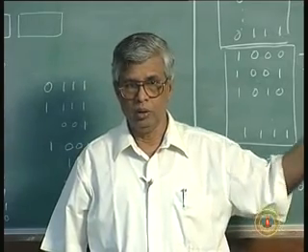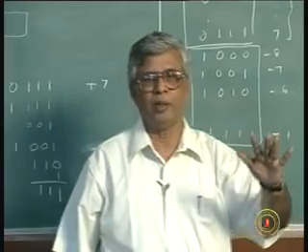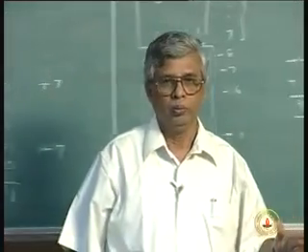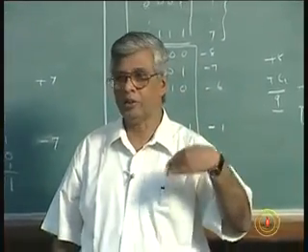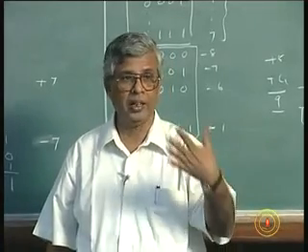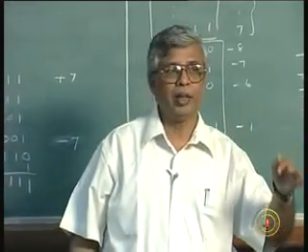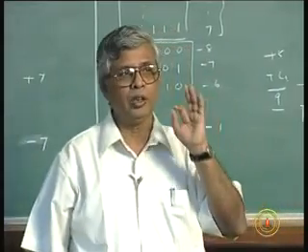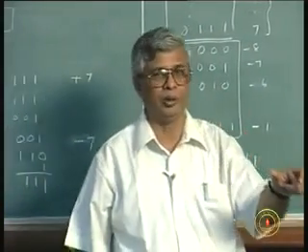So first question, how many bits are there? Second question, what form is the number to be represented? So 4 bits, one of them is sign bit, then we say it's 2's complement representation, then a negative number is converted to 2's complement. Then do an addition or subtraction, always making sure the result is less than what can be represented using the 3 bits magnitude and 1 sign bit.